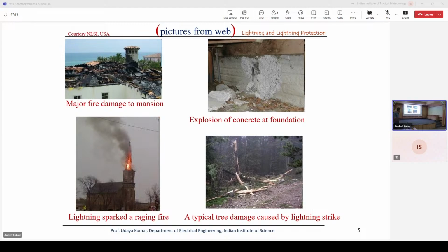And another question mostly asked by people is, can we use RCC structure, the steel in the RCC, as the down conductor for conveying lightning? Normally for houses, we don't prescribe that because the overall cross section is small and the voltage and field levels are very high that can puncture the concrete. Concrete is a porous structure. The micro wires will have air discharges during the event. The pressure developed by the discharge can rupture the concrete. For a very huge structure, we can still use the foundation or the RCC steel as the down conductor.